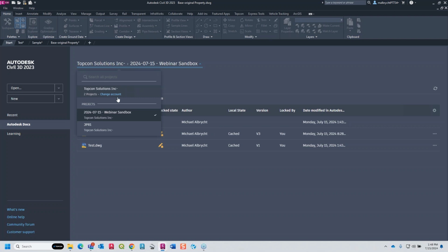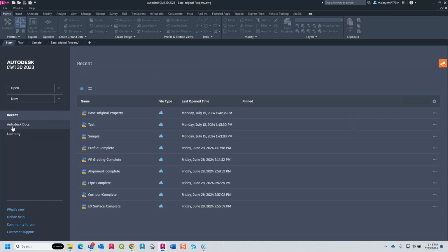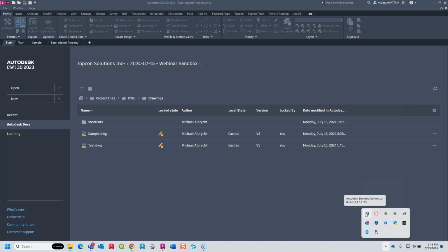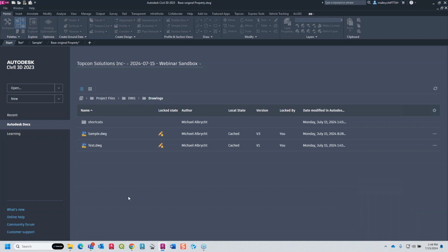So this Autodesk Docs, though, you probably do not see currently on your Civil 3D file. That Autodesk Docs portion is unlocked as that direct connection access point between the ACC and the Civil 3D software from that BIM Collaborate Cloud license. The desktop connector as well is an additional download. The desktop connector is its own individual software. You can get that in the same place you download your Civil 3D products. So where you get Civil 3D under products and manage in the manage portal, there's a little desktop connector location as well. And there's a product download for that desktop connector.